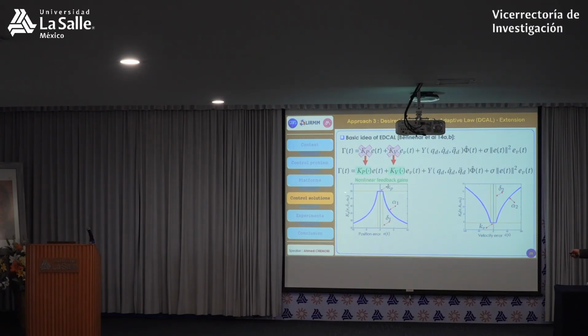And then you can ask me why we put a threshold here, on Kp. Because if we continue the exponential, it goes to infinity. If the error goes to zero, and we continue this exponential, it goes to plus infinity. And we have to avoid this. This is why we limited the maximum here, and this is a saturation or a threshold. So this is Kp, the same idea for Kd, also for small and big errors, and we obtain this.